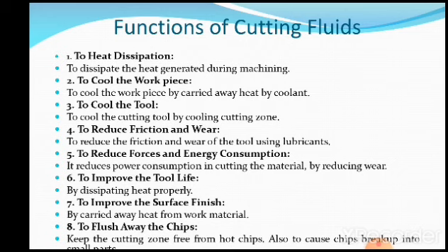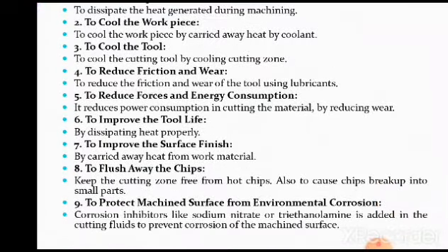To improve the tool life by dissipating the heat properly. To improve the surface finish by carrying away the heat from the work material, because the work material will get the required amount of surface finish if it is not overheated.